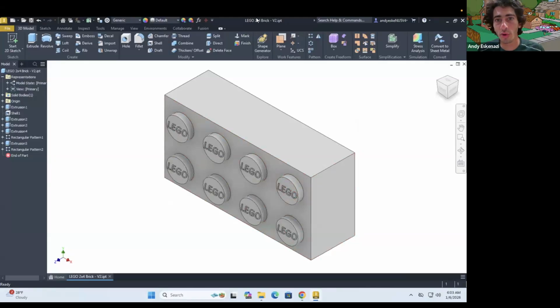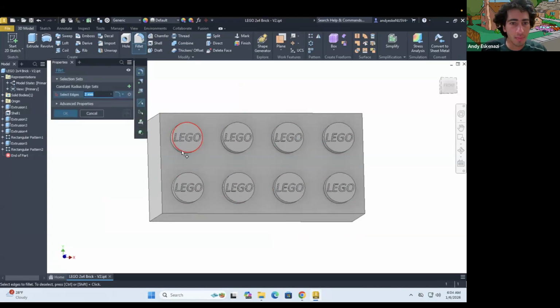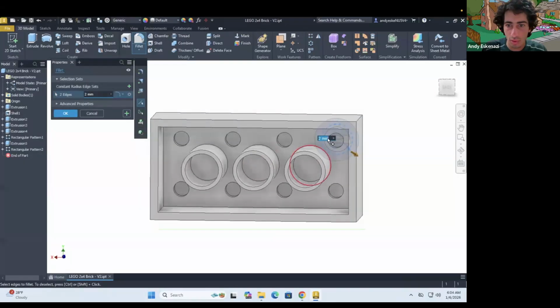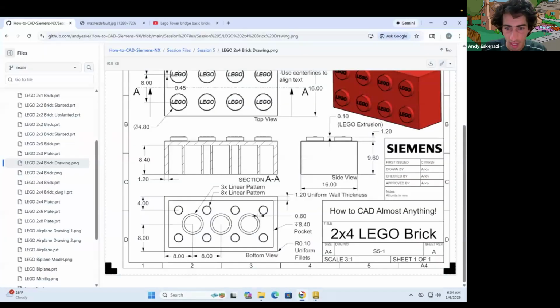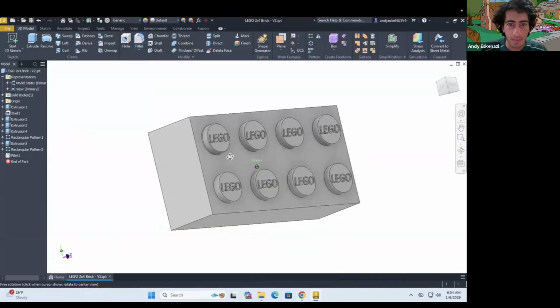All right, so I was able to create just a second ago a copy of this brick, which I'm writing right there as B2. So what I'll do is I'll go here to fillet, and really I'm gonna just go here to all of those edges. I know it's not happy about it right now, but we know it's a fillet of 0.1. So I'll click on that.